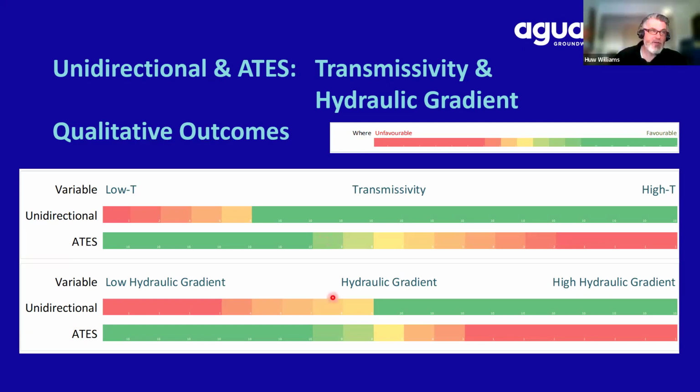And as you can probably conceptualize with the aquathermal energy storage system, with a very high hydraulic gradient beneath the site, our nice bubbles that we want to create move off. They move down hydraulic gradient as a nice long plume, and we never see them again. That comes with many caveats of how the loads are balanced and how the system is pumped. But essentially, that's true for a doublet single pair system.